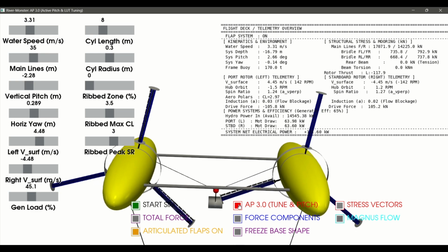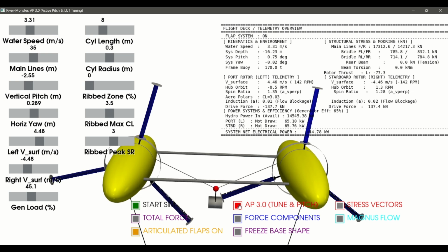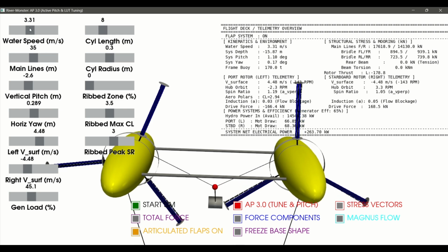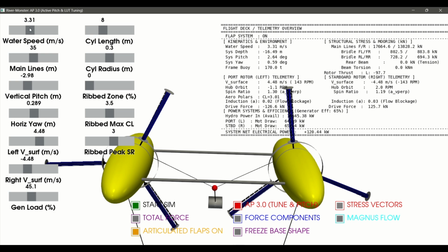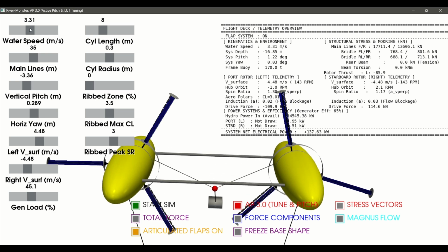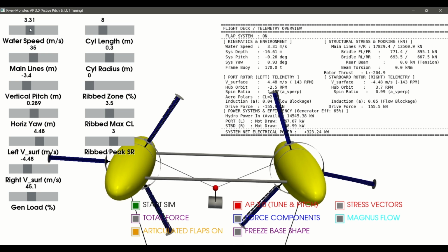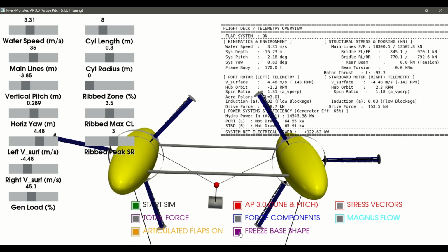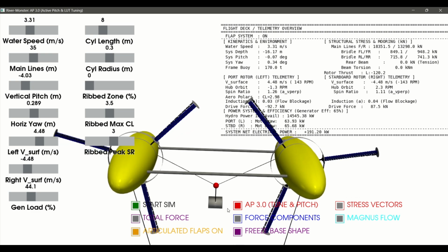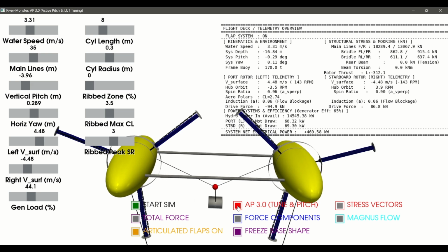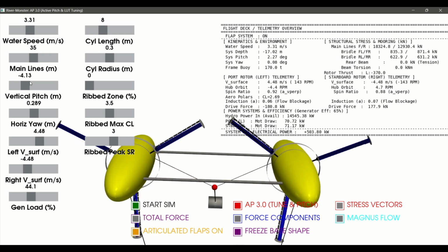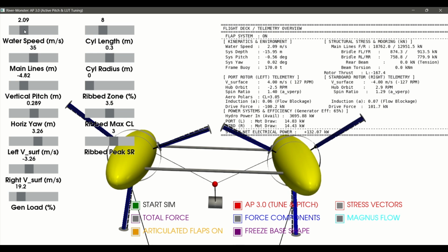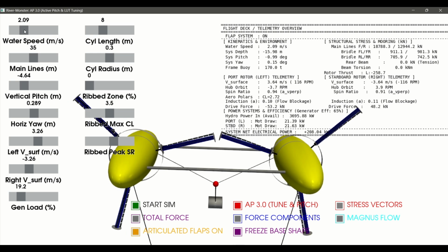To validate the engineering rigor of this model, we will conduct a final extreme test. In the physical prototype, the central backbone of these flaps is a rigid metallic C-bracket, geometrically optimized for a specific high-velocity design point. We lock this base geometry and disable the autopilot. If we now dramatically drop the water speed, watch how the elastomeric flap segments hinge and fold to adapt to the new apparent flow vector, creating a visible kinked misalignment.